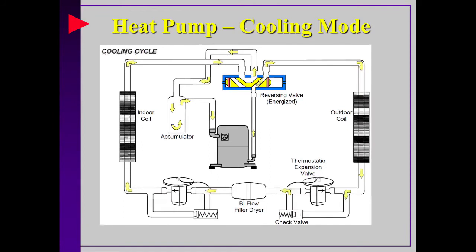So now we go into the cooling mode. Now in this cooling mode, you'll notice how the reversing valve has redirected the hot gas to the outdoor coil, which will now act like the condenser in this case, and this side will act like an evaporator.